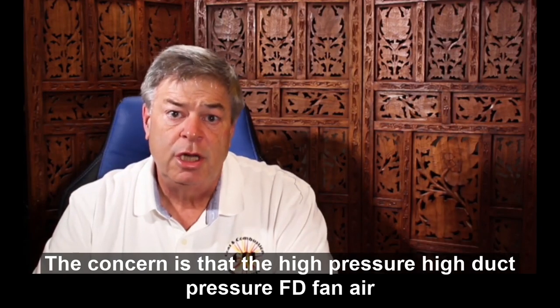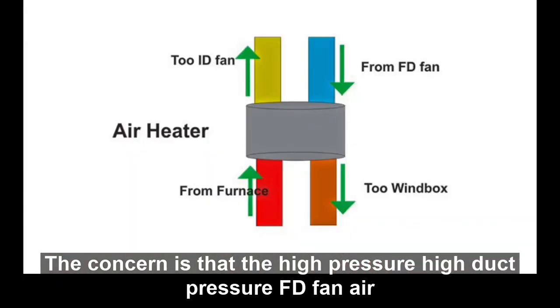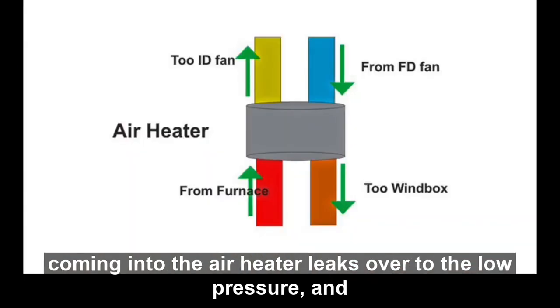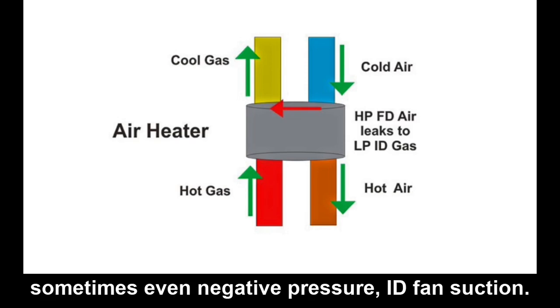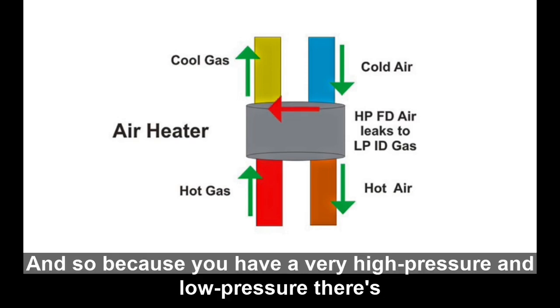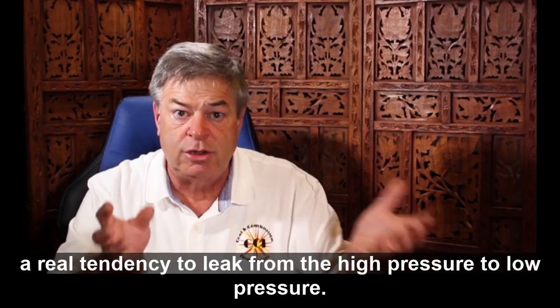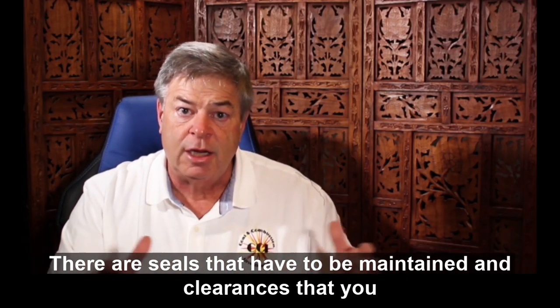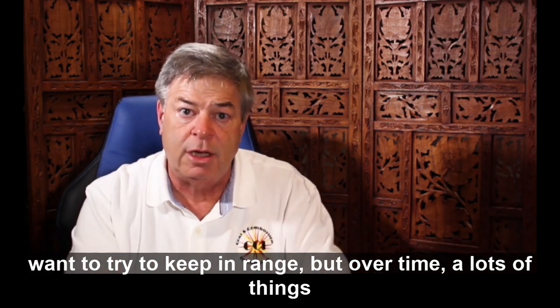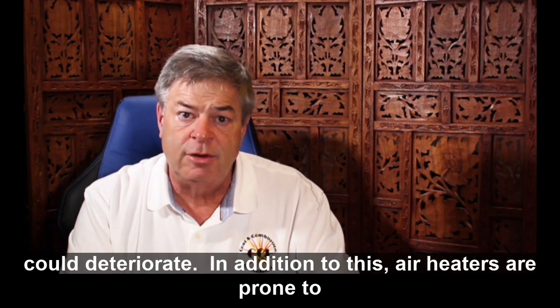The concern is that the high pressure, high duct pressure FD fan air coming into the air heater leaks over to the low pressure and sometimes even negative pressure ID fan suction. And so because you have a very high pressure and low pressure, there's a real tendency to leak from the high pressure to the low pressure. There are seals that have to be maintained and clearances that you want to try to keep in range. But over time, lots of things can deteriorate.